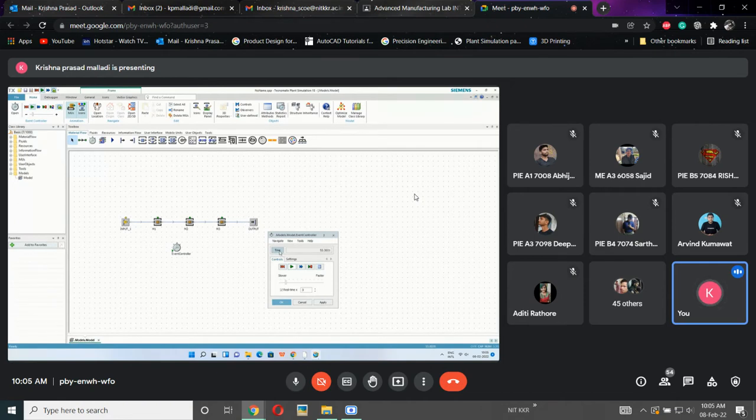So here the movement is not visible. Not visible, meaning in 2D it looks like this. If it is 3D, or if we are using a conveyor here, then the material handling between station to station is visible. That is why I told you in the starting. This connector is just a representation, which means this machine is connected with this one. Once the part is ready with M1, it will automatically enter into this one. The material handling is not going to be visible with these connectors. Instead of this connector, if you are using conveyors or something, then the material movement is also visible with those.